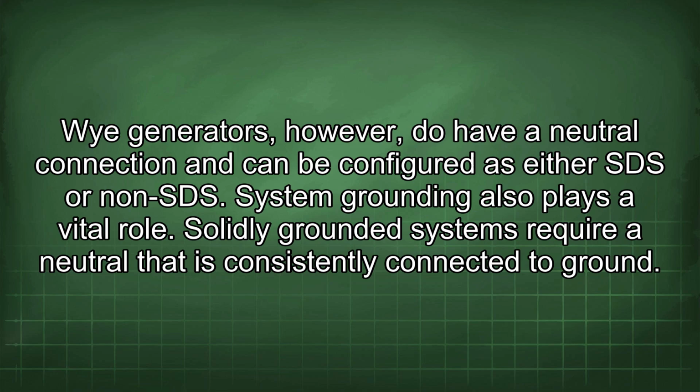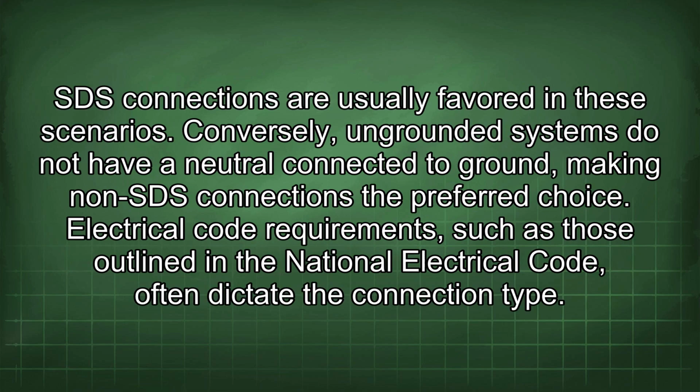System grounding also plays a vital role. Solidly grounded systems require a neutral that is consistently connected to ground. SDS connections are usually favored in these scenarios. Conversely, ungrounded systems do not have a neutral connected to ground, making non-SDS connections the preferred choice.